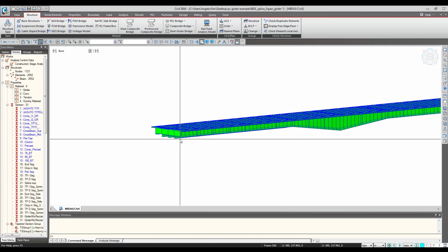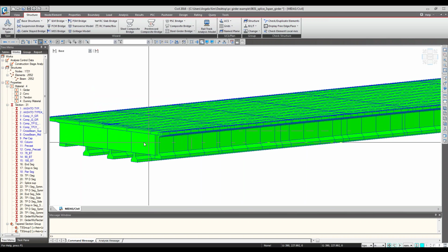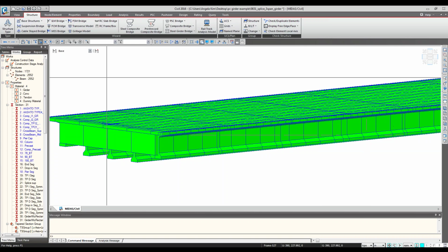This applies not just to changing a dimension of a section, but to changing the entire section from H-2 to H-4, or from one of your DOT sections to a different DOT section. If you define a different section, you're able to run the wizard data over it as many times as you want.